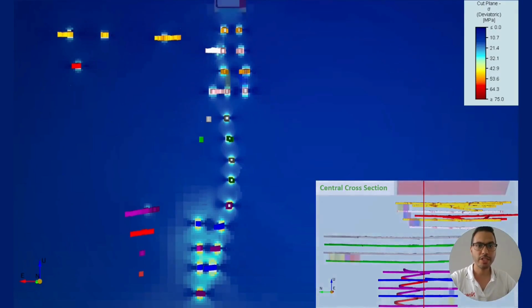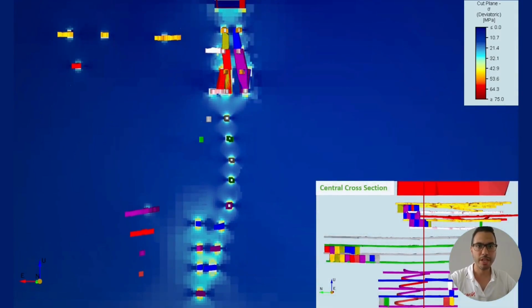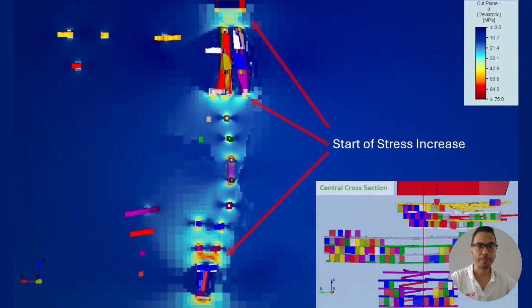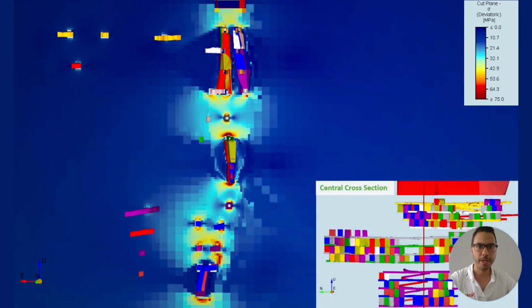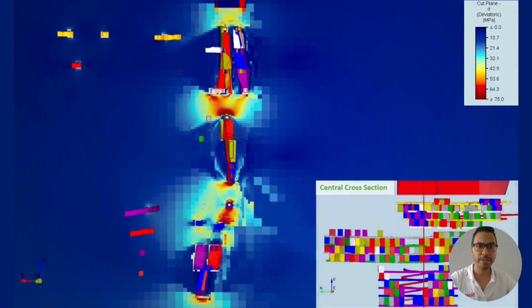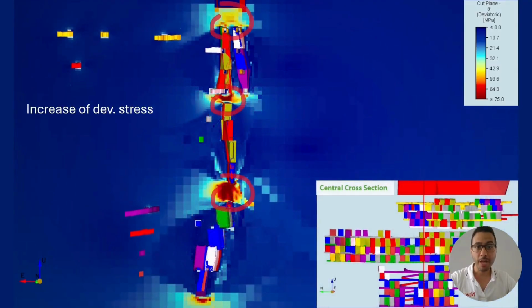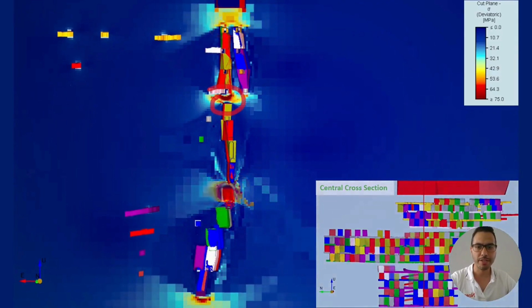As we are advancing in time, we start seeing an increase of stresses and interaction between levels. As we are mining from bottom to top, we keep pushing the high stresses into the rock pillars, including the sill pillars. These are indications of potential increased seismicity for seismically active mines and instability of the adjacent galleries. We can, for example, query stresses at a particular location and plot them to evaluate the stress path and understand when issues may start arising.